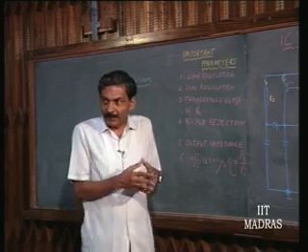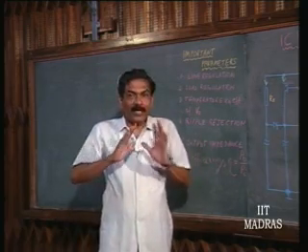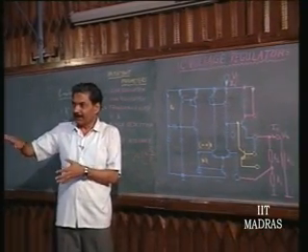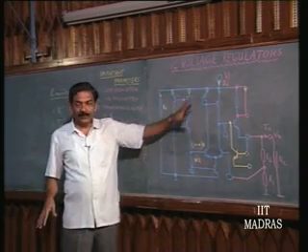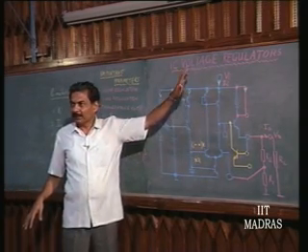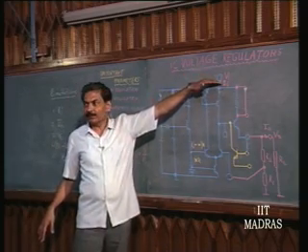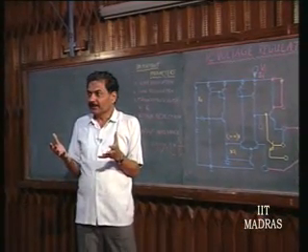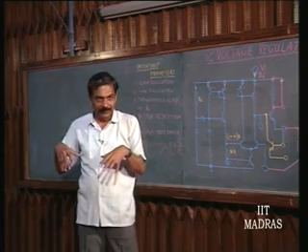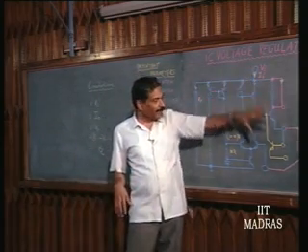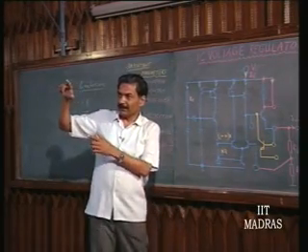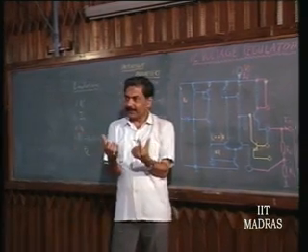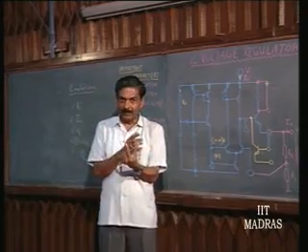Yeah, it is primarily related to that. What is the idea of this efficiency? Actually, we do not want the regulator to be used at all. When we are designing a separate system, the voltage regulator is an accessory. Why does it become necessary? Because if we directly use this voltage, our operating points will keep shifting, and we have to make our design more complicated. So, we would like this voltage regulator to give us a supply which is relatively independent of the input voltage. So, this has been inserted in between your system and the input power.